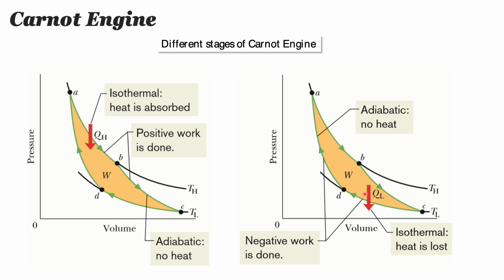Now going back from here, the gas is compressed under a higher pressure, the temperature increases, but the excess heat is transferred to the low temperature reservoir, and the temperature is maintained at TL. Since the gas is compressed, the work done is negative and the temperature is maintained, therefore this process is an isothermal process.